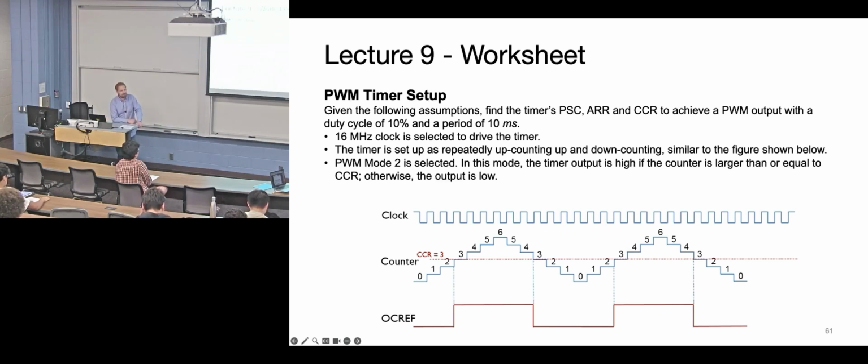I have a question kind of following that. Is it resource intensive to turn it on and off? Would that be why a triangle's better? You just stay on for longer? Well, you can get double the count out of your register, right? So you can basically go twice as long. You may have some point of view where you're like, I have this clock, I can't change it. I can't change my prescaler for some reason, and I just need to go double. So this would be a way to get you a longer period of time. It may be that the math you're doing, in C-land or something, just happens to be better posed with this sort of structure. I can see that being the case.